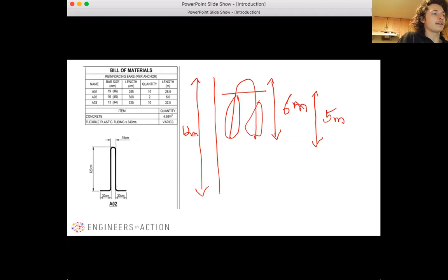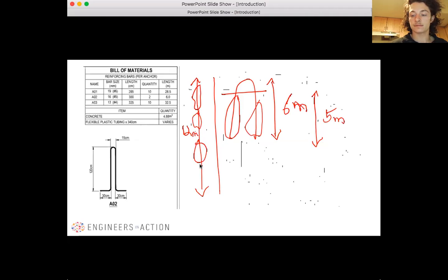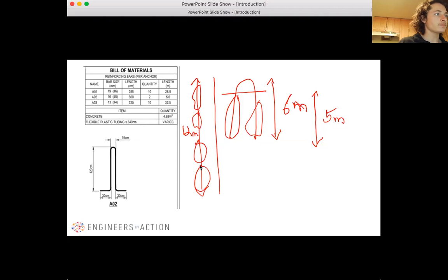We go back to the beginning with a 12-meter bar. Theoretically, we could cut 4 sections of 300 centimeters to bend AO2. However, with the same amount of material, because of the construction process, and in this case, more of the procurement process, we are only getting a realistic 2 sections of AO2 from a 12-meter bar.